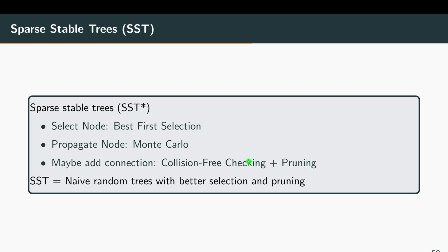Yeah, you include everything. So it's really like you sample a 5-dimensional vector, for example. For a car, it depends on the order of the car. If it's a basic car, then it's just x, y, theta, so you sample 3 dimensions. But if you have a second order system where you also have velocities, then it's suddenly 5-dimensional. And you do sample that as part of your random sampling, and it also is part of your distance metric.